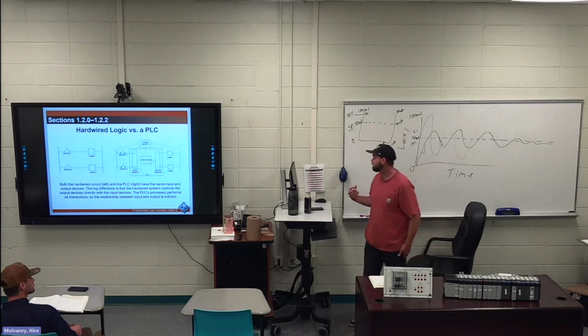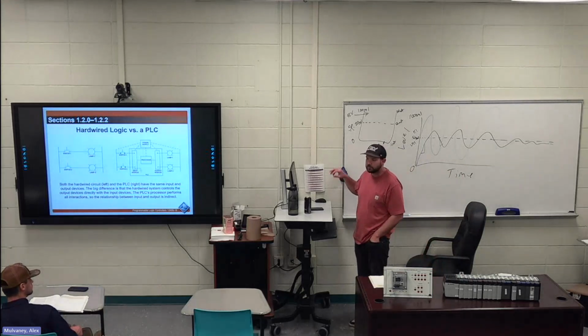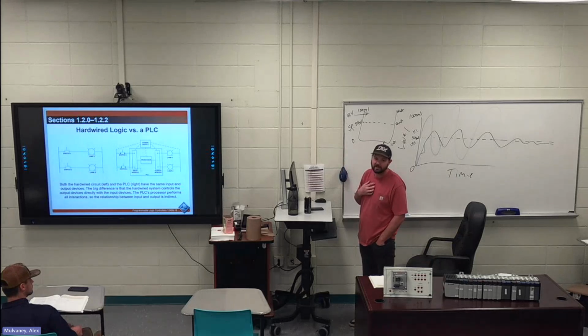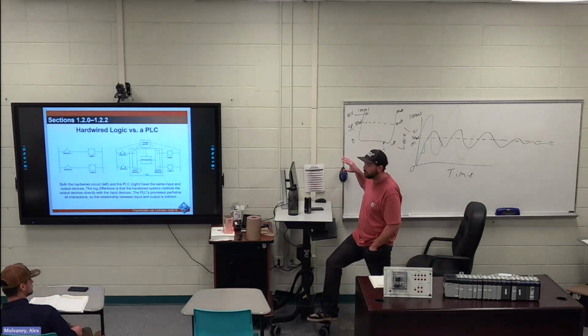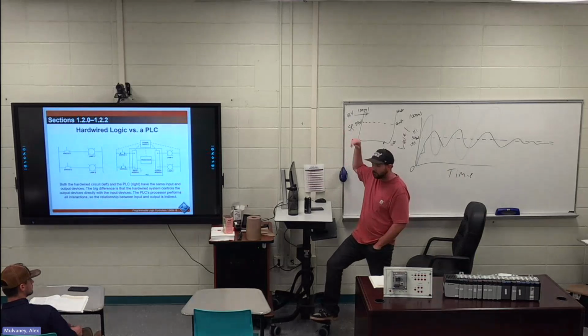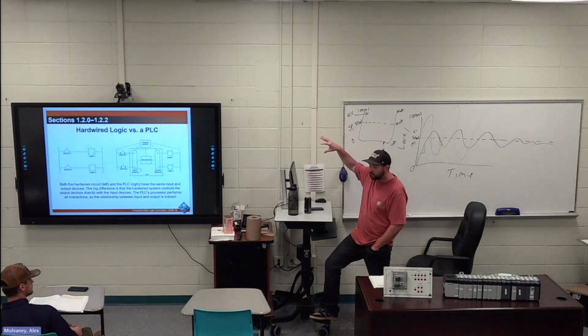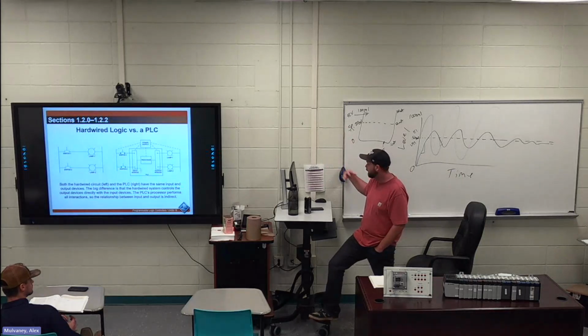In my experience, I didn't do a lot of PLC programming. I wasn't going and getting devices and getting the inputs and outputs. I did troubleshooting. So PLC troubleshooting was amazing because instead of walking all over the steel mill, 3,000-degree ovens, looking at gauges on the side, I could sit in a room like this and look at the computer screen. I could pull up HMIs that the operators had, but I could go see more than that and look at the actual inputs and outputs, scrolling through a computer and see, that looks jacked up.